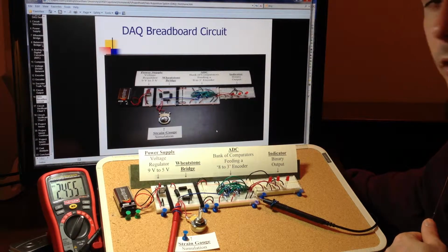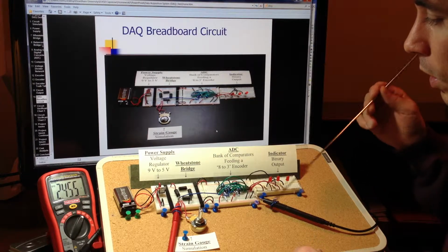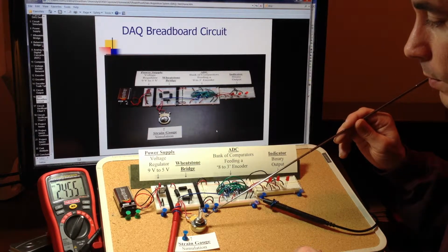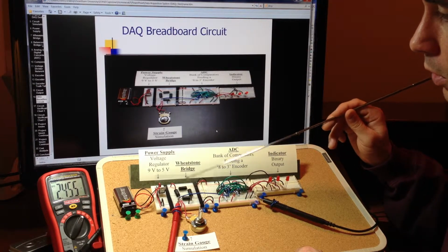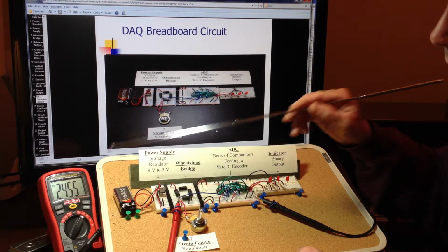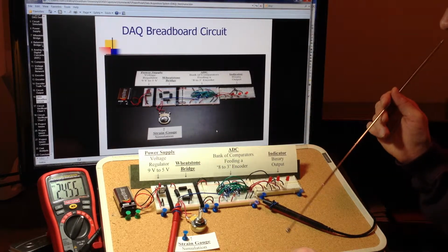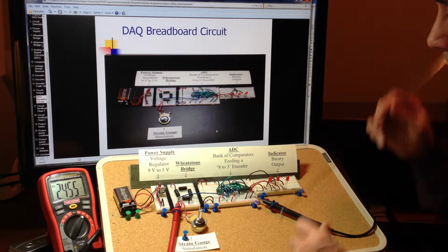And now I will show you the operation of the circuit. As I increase the potentiometer, it's going to increase the resistance in the Wheatstone bridge. The multimeter will then see that difference in voltage, and it's going to be a change of about 80 millivolts. You will also be able to see the change in the LEDs here.